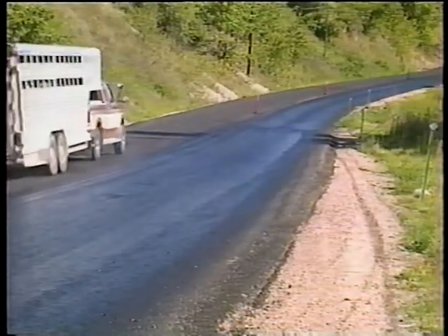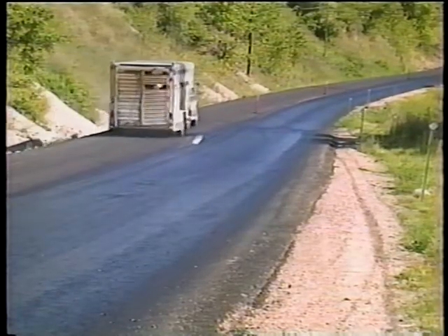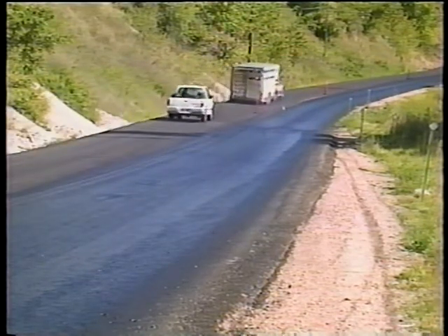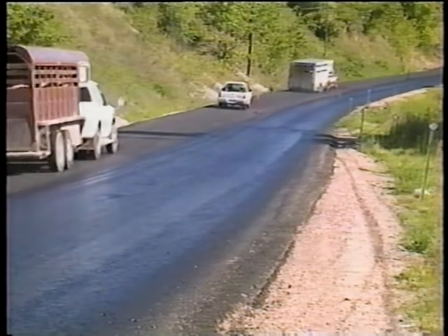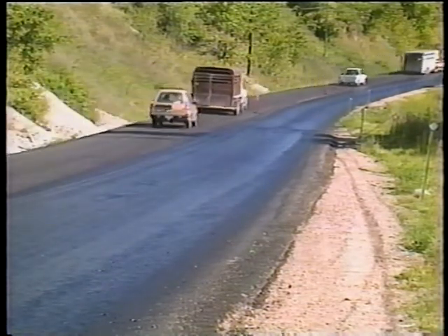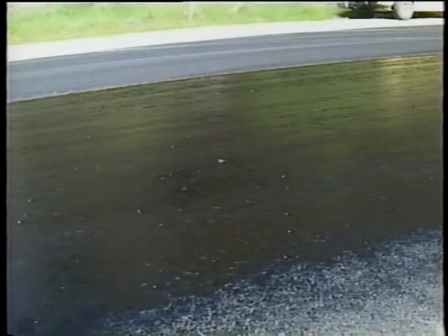Here are some more points about the tack coat. Don't apply more tack than can be covered the same day. Also, be sure traffic and dirt are kept off the tack coat. Both will hamper the bond. When emulsions are used, make sure the material breaks, loses its water content, before the mix is placed on the surface. You know this has happened when the tack turns from brown to black and becomes sticky or tacky.